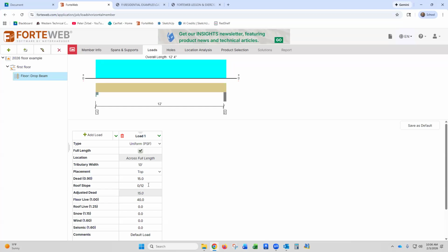So our floor live load, based on their code, is 40, which is good because Wisconsin's code is also 40. Now, Wisconsin does not use the International Building Code, as we're going to find out. We still have something called the Uniform Dwelling Code. Wisconsin is very proud of their code because we were one of the first to come up with our own codes. And the builders love the Wisconsin code because it doesn't require them to do a lot of the energy efficiency things that the International New World Order Code does. So Wisconsin fights to keep their own code, but we're still at 40 pounds per square foot.